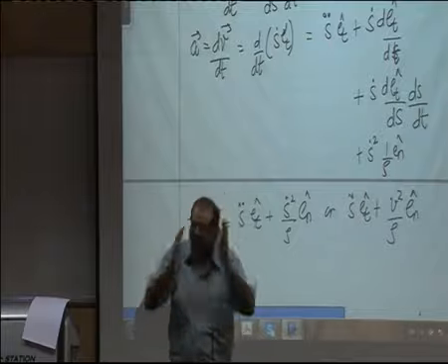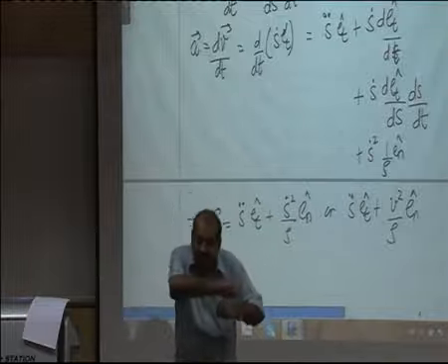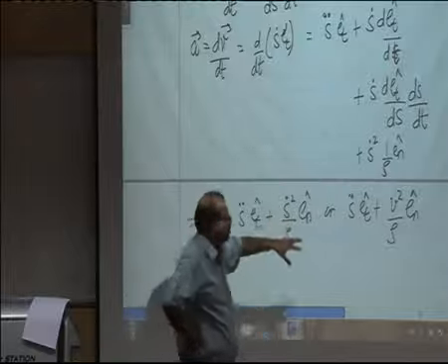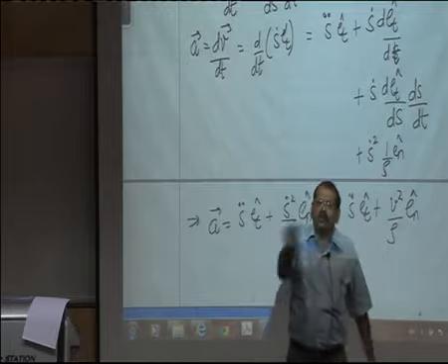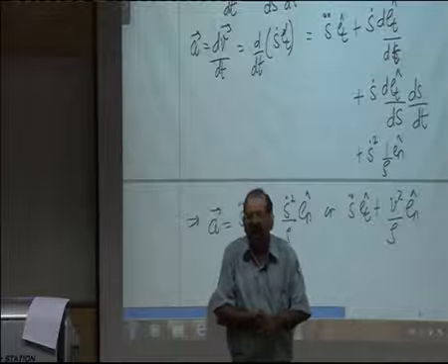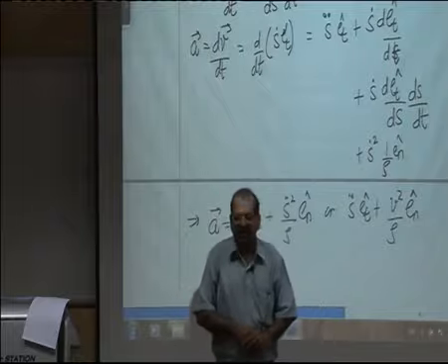So, wherever you are getting a bit confused in a curved path, think of path coordinates and ask whether you can find the radius of curvature. Essentially, if you have to use path coordinates, the main thing will be how do you find rho. If it is a circular path, then rho is quite straightforward. It is just the radius of the path. If it is not, we will see how to find that.